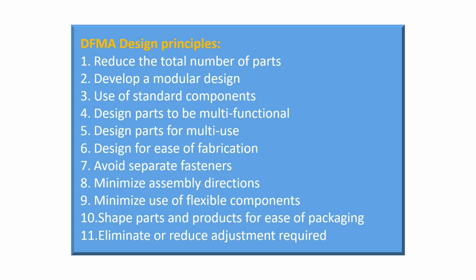9. Minimize the use of flexible components. Flexible components include rubber parts, straps, gaskets, cables, etc. Flexible components are generally more difficult to handle and assemble.